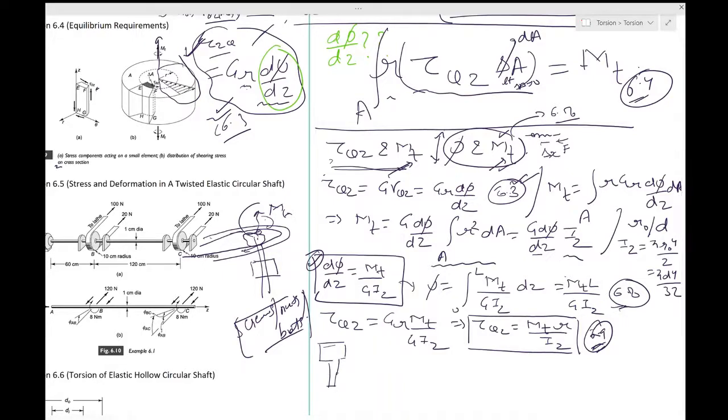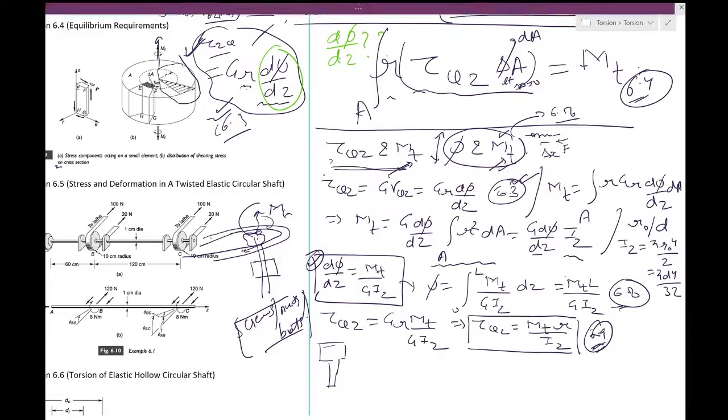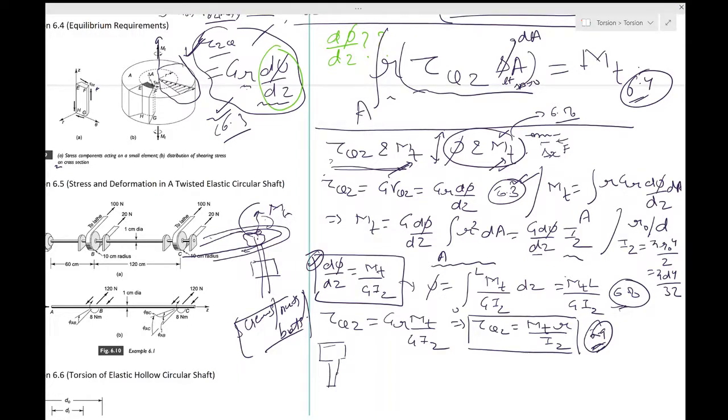But again, that's the whole point. By Saint Venant's principle, which we have discussed before, if you have a statically equivalent boundary condition, then the solutions which are far away from the boundary are approximately the same. That is the reason why these results are still taken and found to be working despite the boundary conditions towards the end of the beam being slightly different.